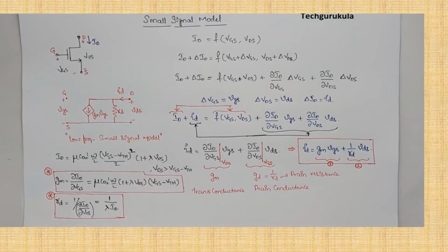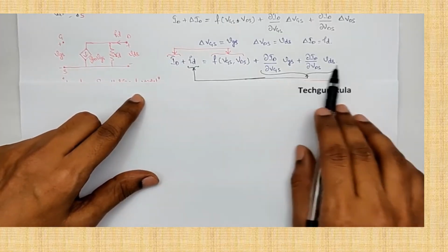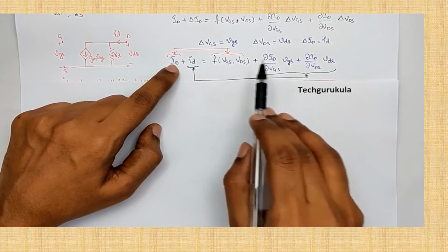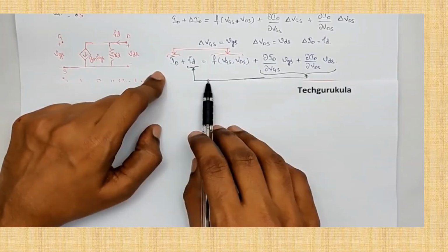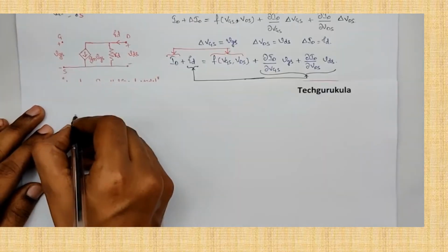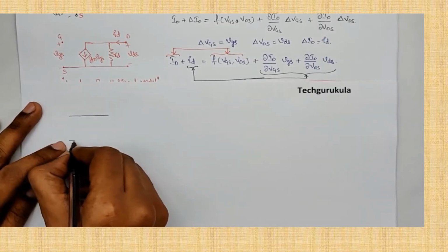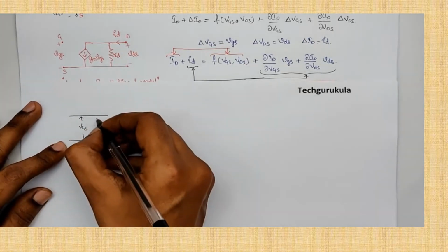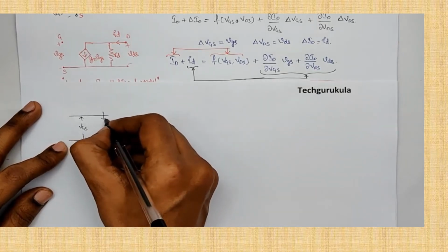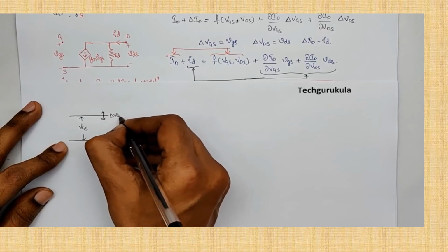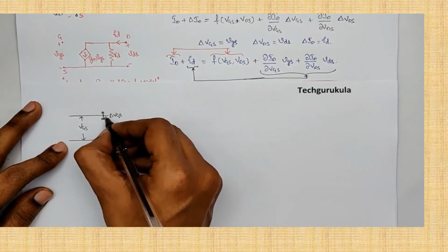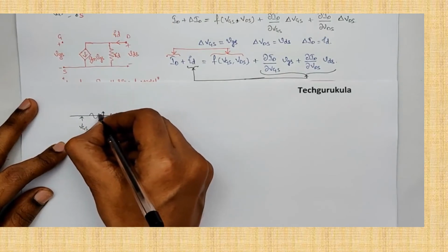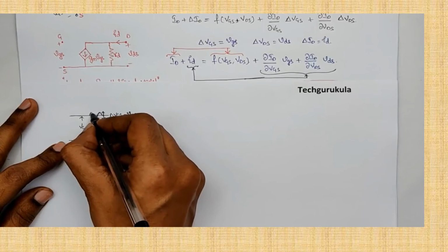Now let's see the philosophy behind the small signal model. Let's start from this equation because it contains both the DC current because of the DC voltage applied and small signal current because of the small signal voltage applied. Now if you look at this, the assumption with which we started was that, let's say there is VGS, which is with respect to time, VGS is constant, capital VGS, and we are assuming there is a delta VGS that we are changing on top of it. Let's say that delta is around this value. Let's say this is delta VGS. We said this change is very small, so that we equated this to a small signal VGS. So let's say this might be a small sinusoid that is riding on top of this big DC VGS value.